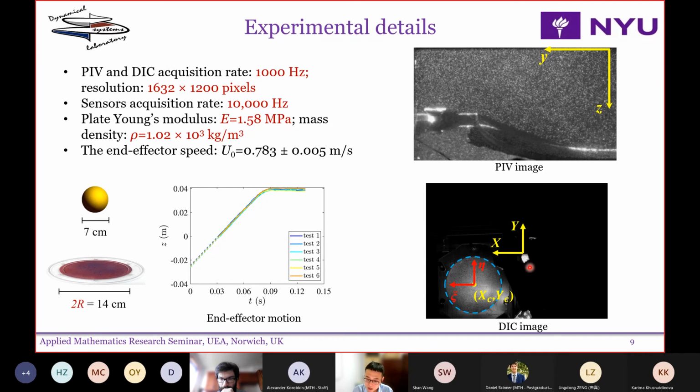the image. The reason is that we did it on purpose. We want to use the perspective of the camera to compute, from the in-plane displacement, an out-of-plane displacement. And to do that, we need to put the panel on the side of the image and then use the perspective of the cameras. I will use another slide to explain this in a little bit more detail.